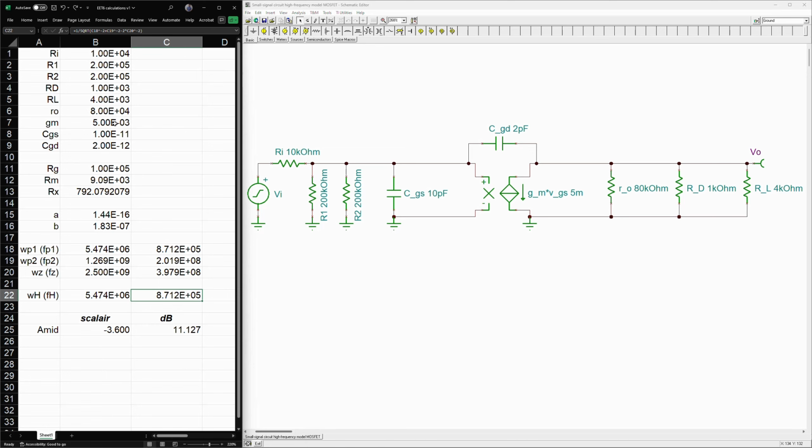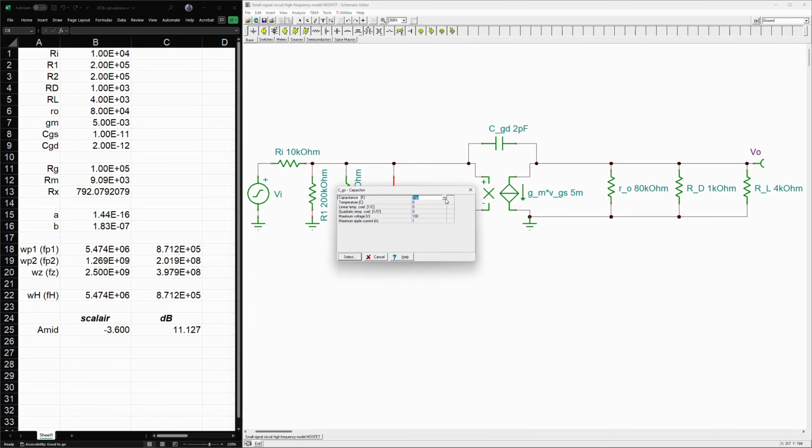What I would like to know is what happens if you, for example, change one of the parameters here. Now, usually if you change the capacitor, if you increase that, you expect that the upper cutoff frequency will be lower because the time constant will be larger. We can check that in Tina TI SPICE very nicely by selecting a control element, or control object. I click on that one. For example, if I want to see the effect of CGS, I can click on these 3 dots, and I can say let's make a list.